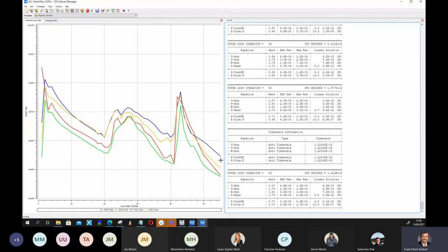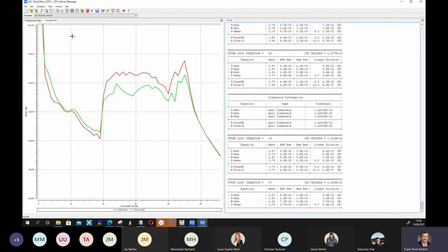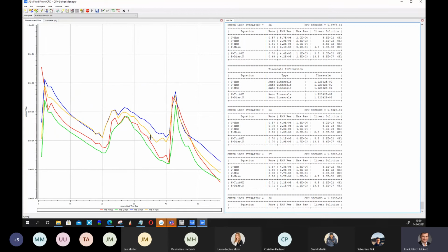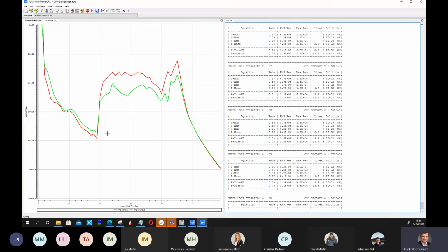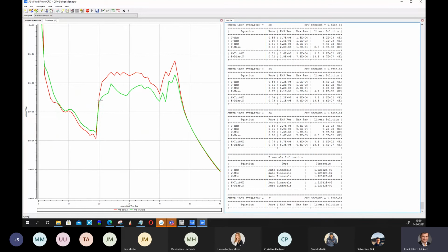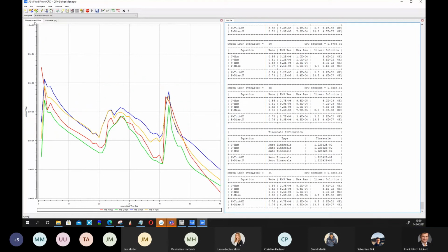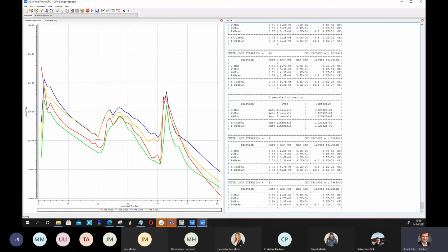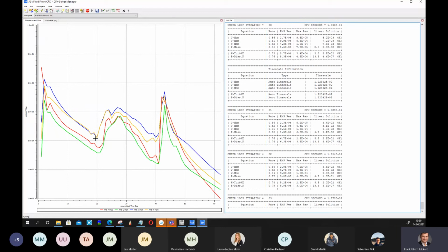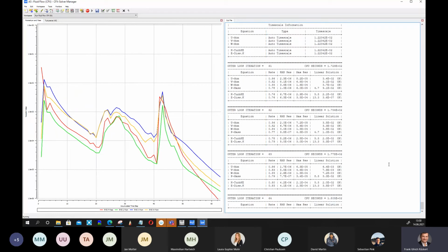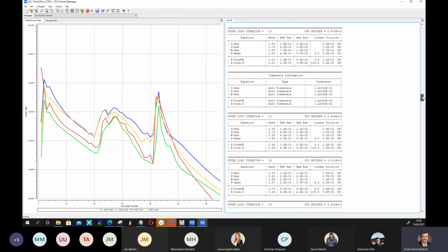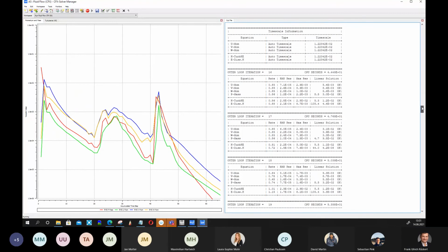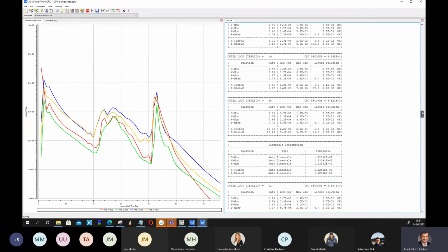But we are at least at 10 minus 4. Here you see turbulence. Turbulence is also high in this region, and it started at iteration 20. Something happened here, iteration 20. Maybe we can look into the out file here at 20.